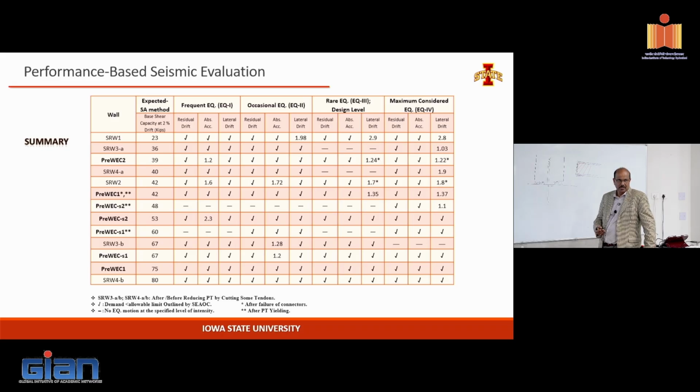And precasters would love it because of the very simple detail, they can cast these panels and transfer them to the site fairly easily. So, even though we shifted more towards seismic, I want you to think about non-seismic and how one can simplify these details and deploy it for a non-seismic application.